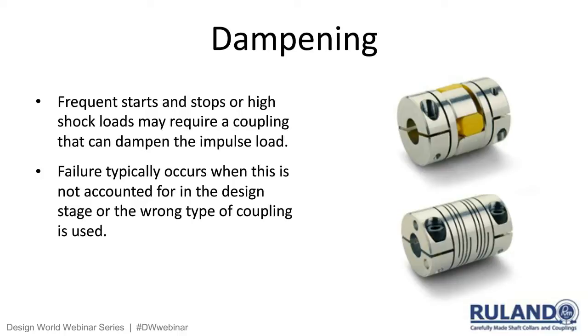Bellows couplings, again, don't have any dampening characteristics to them. And if you're too aggressive with your starts and stops, you're going to have issues using bellows couplings and beam couplings. You're going to have to take that into consideration.